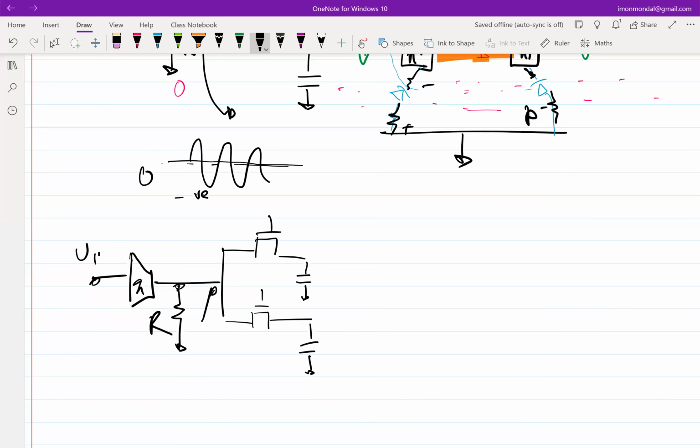You can give many things. This is a small thing. If you assume this to be a small signal ground, right? So you can obviously give a battery here, right? So lift that voltage. And if you do not want to take that risk and say that, okay, I didn't know this, this can be weak, then you can have a separate resistance, some V bias resistance here, right? So that can give you the requisite amount of voltage at this node.